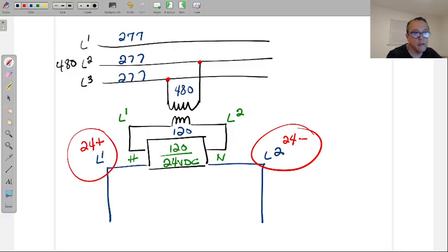So when you're troubleshooting something like this, assuming again that we have some fuses up here, these would be all of the things that you would have to now trace down, right? As I was saying when we started, this is kind of why, George, I mentioned that about where do we start, because I like to start at power, because look at all the things that could actually require some focus. If I go to measure my L1 and L2 on, let's say, a 24 volt DC power system or control system, and I don't have it, I got a few things that I got to go look into.